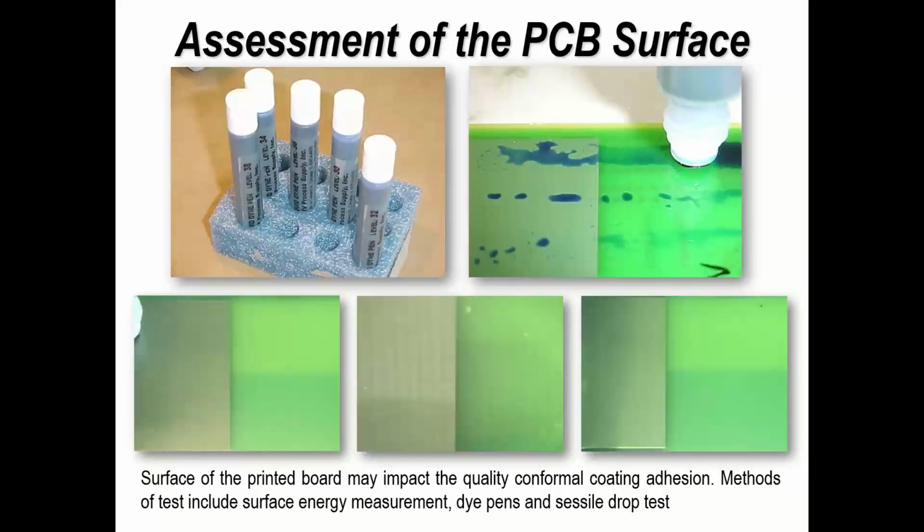So as a simple example, another thing is knowing the wettability, the surface energy of the board with the solder mask on before and after processing. What these are is dyne pens. They're giving you an indication of the surface wettability of a test fluid.